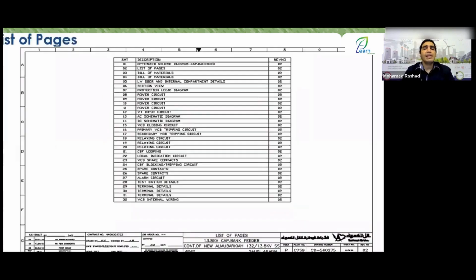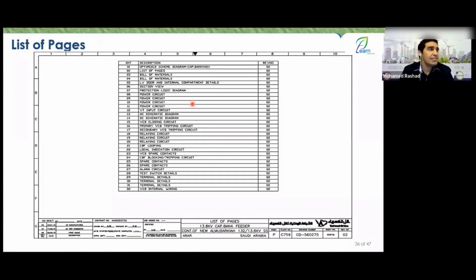So how will this help me? It will help me if I now enter a Schneider station. I've been working with Siemens all my life, and I enter a station, let's say not a Schneider station, but an ABB station. So what is it, engineer? I came to the operations guy and asked him what problem he had. He told me, well, the breaker isn't closing. Okay, the breaker isn't closing. Yes, then there is a problem in the control circuit of the circuit breaker.